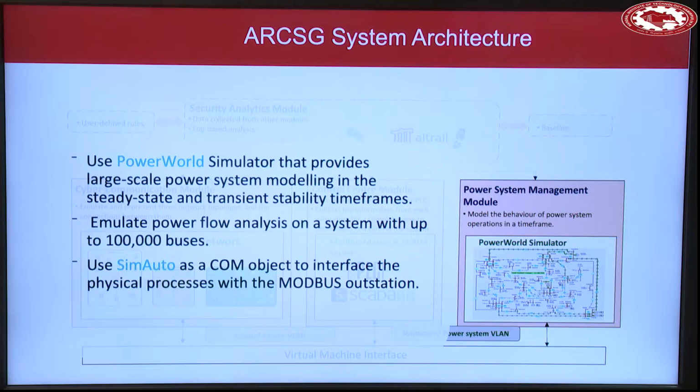They have some functionality called SimAuto. SimAuto allows you to connect. For example, if you have an interface, what we can do is create a tool in Python, a communication interface or whatever, and connect Python to this software through the interface called SimAuto. If I'm making changes on the interface, I'll show you how it works later. I can pass that behavior into the simulation and then run it. So I can attack on my Python module, pass those changed values to PowerWorld, and then simulate it. Again, it's supporting the Modbus protocol.